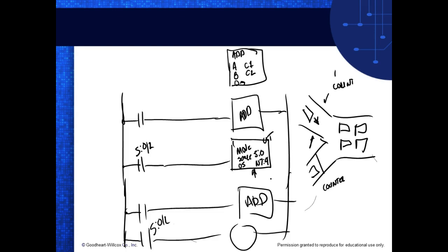By the way, what we would do, and we'll learn that later on, is we would mask it off. Masking allows us to strip off bits that we're not concerned with. S0 is a 16-bit register, right? But all I'm interested in is bits 0, 1, 2, 3. So we would like to get rid of those bits that we're not interested in, because they're going to bring in something, right? Later on, we'll learn about masking. We use a move with a mask, so you can actually strip off the bits that you don't want with one instruction.